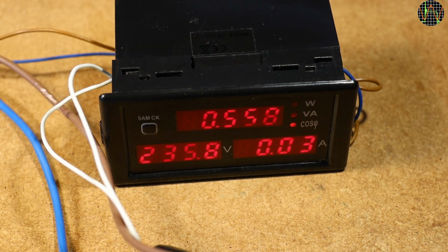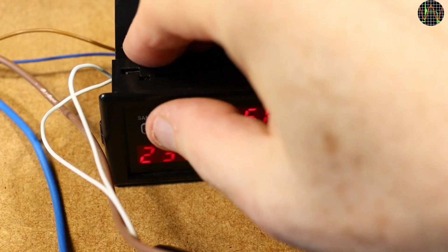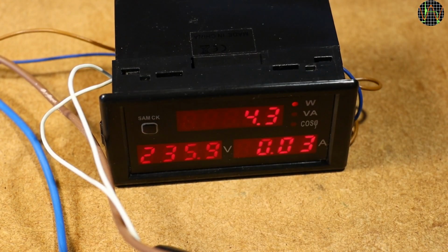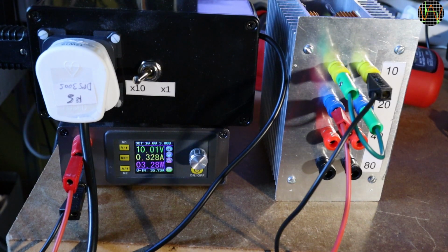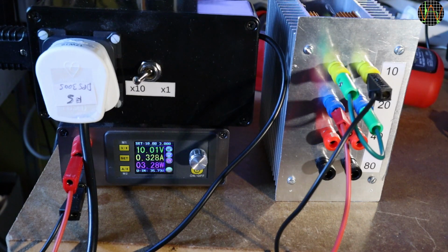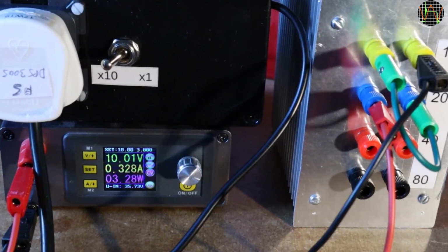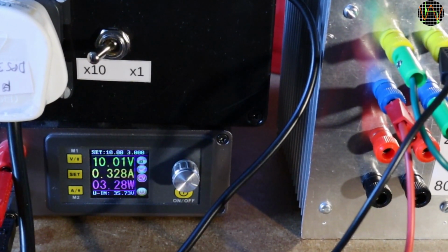The problem with this approach is to find test objects that have different power factors and that draw a decent amount of current. The latter is needed because this panel meter does not have a ×10 mode, so it needs sufficient current to read correctly. This means more than what an LED light bulb usually draws. In the end, I used a switch mode power supply, allowing me to vary the DC load, hopefully resulting in different power factors. Here it is loaded with providing 3.3 watts DC into the power resistor.